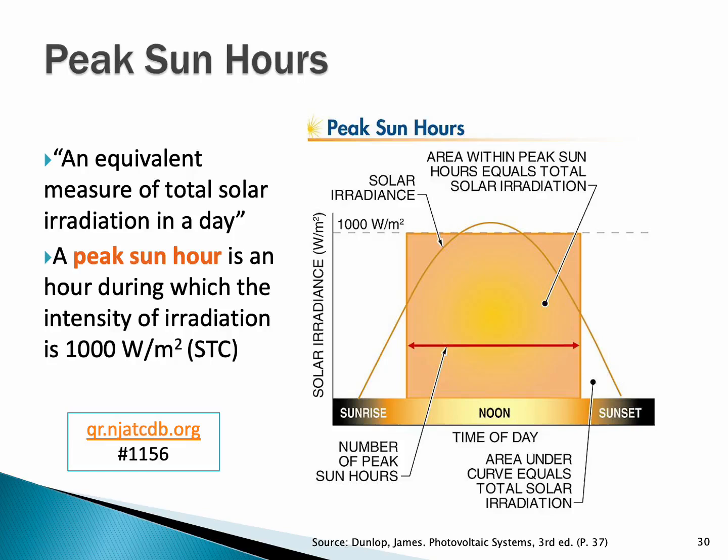I don't believe we've seen this before, peak sun hours. We've talked about sun hours. What they're talking about is this. When the sun comes up, we get a little bit of irradiance and a little bit of watts per meter squared. And as time goes on, we get higher and higher performance and output of the system. And at some point, roughly around perhaps 10 o'clock or so, till 2 o'clock, we'll get this peak performance, which is about 1,000 watts per meter squared.